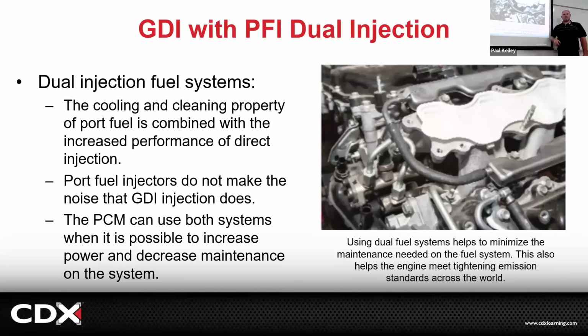So you've got a V8 with 8 direct injectors, and you add another 8 port fuel injectors on top of it. You've got direct injectors down here, and port fuel injectors right here, and we'll go back and forth between the two in a strategy to keep your valves clean. So you don't have to do your walnut blasting and your GDI spray and your additives and your Sea Foam and whatever stuff. So that's a little bit more where the Japanese are positive.